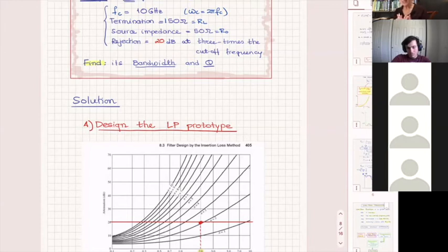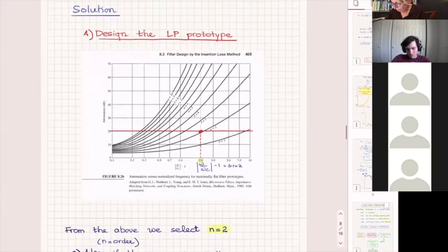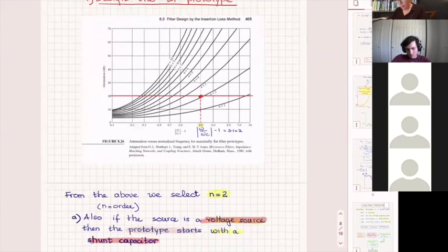And it's not really a section, all right? It's just the last one, we call it n+1. So if, for example, you say my filter has n sections, capital N, that means that I have n resonating elements. So I have a combination of inductors and capacitors. Okay, so I don't know that yet, however.